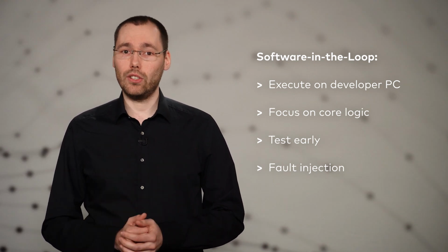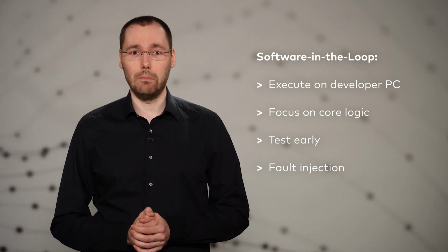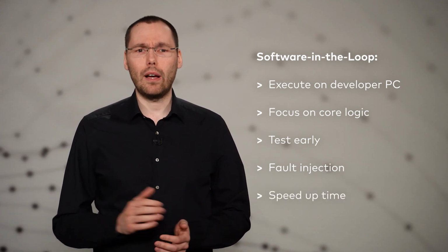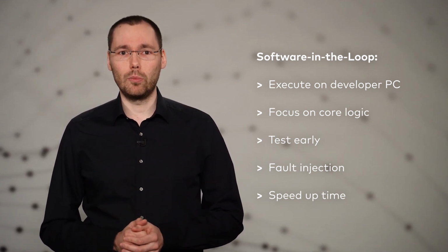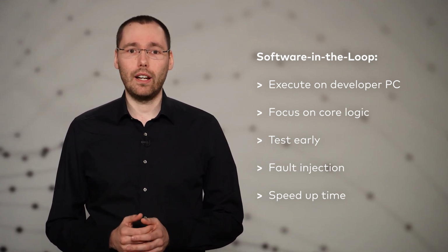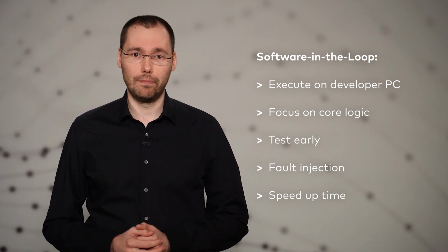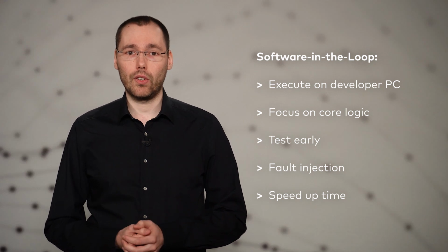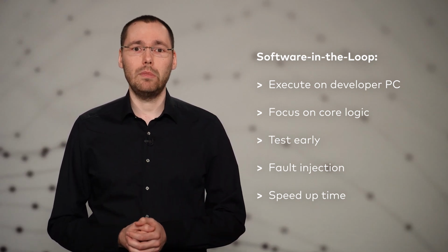There is another major advantage of SIL. It is not bound to real time. Developers can speed up time and run thousands of tests in minutes, enabling fast feedback loops and allowing them to verify the correct behavior of the software over a long period of time. This way, memory leaks and other errors that would occur only after several months of operation can be found within a matter of minutes.